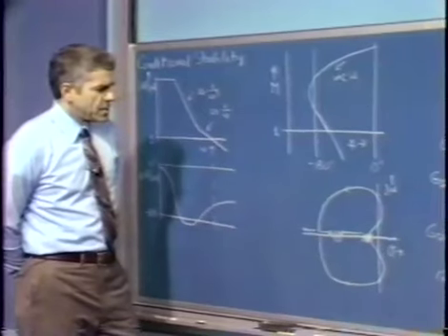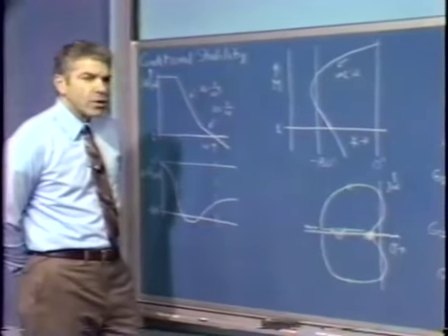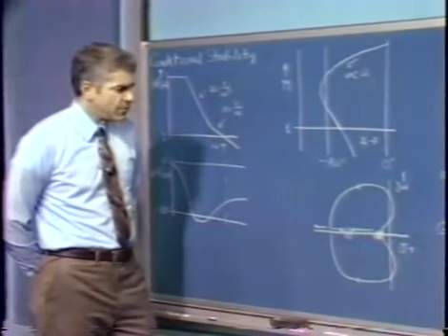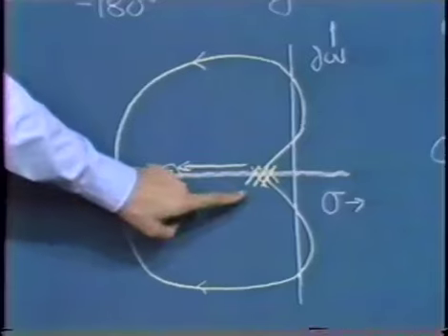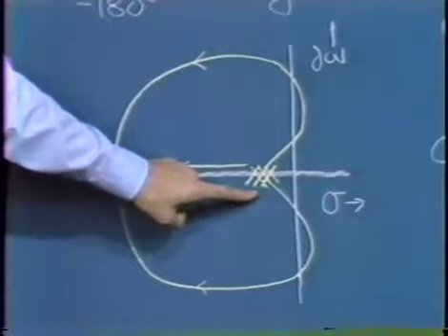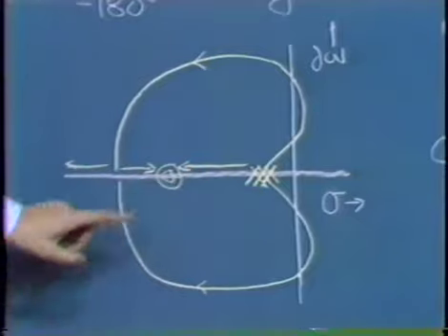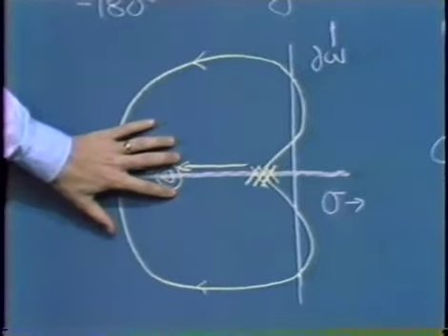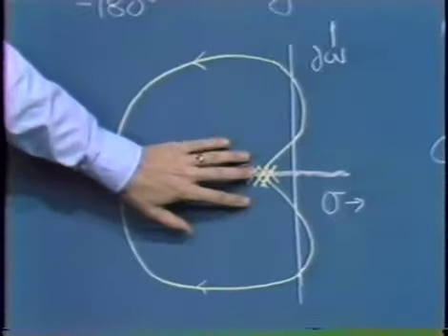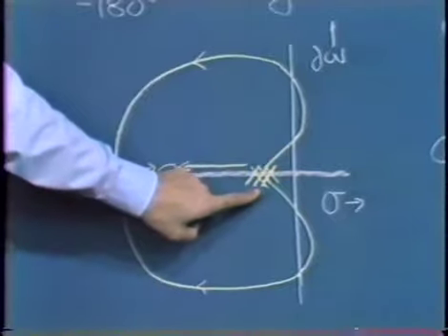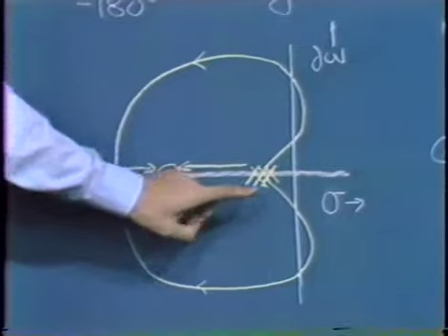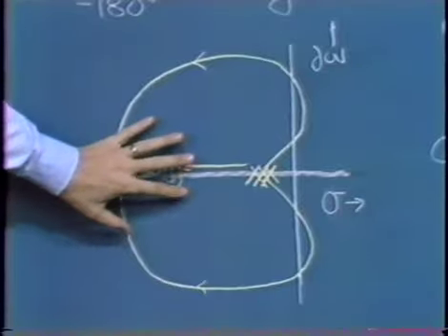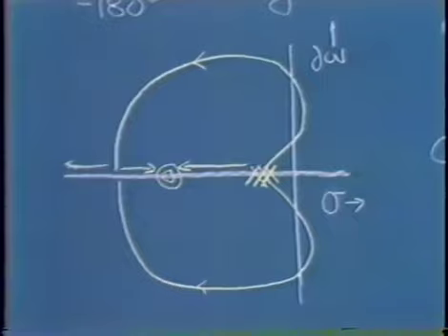We can look at the system in one more representation, and as we go through the analysis, I'm going to try to play these various techniques off against each other so we can see the interrelationship among them. We said that the system has 3 coincident low-frequency poles and 2 higher frequency zeros. Providing there's enough separation between the frequency at which these 3 poles are located and the frequency at which these 2 zeros are located, the root-locus diagram for the system will look as shown.